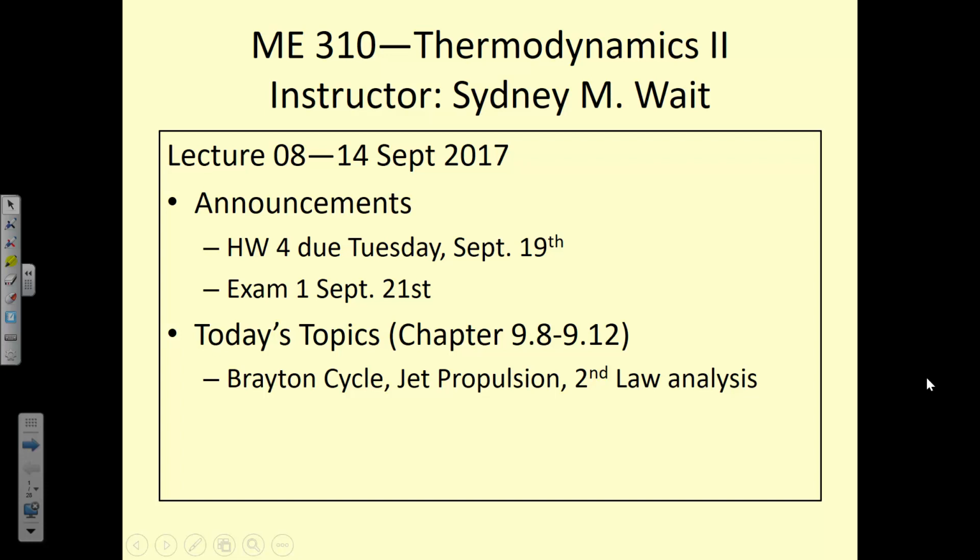So when we're talking about a device like a throttling device or a mixing chamber where it doesn't do any work and there's no heat transfer that's being used for anything of benefit, then the exergy recovered is 0. So our second law efficiency will be 0. The solution will be posted online. I haven't scanned it yet, but it'll be on this afternoon. So if you have questions about how you did on problems and where you went wrong, then please see the solution for that. And hopefully you started the next homework.